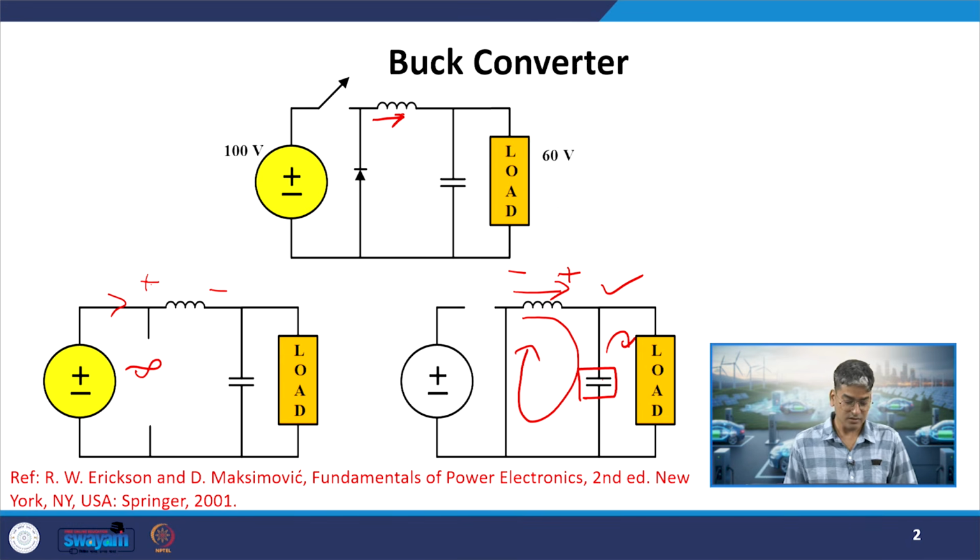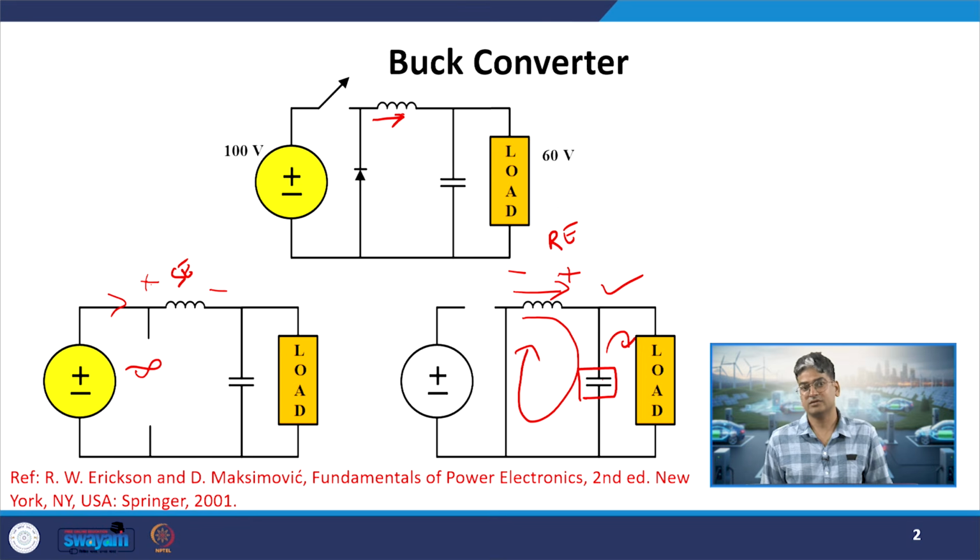Okay. So now coming back to the point which we mentioned while discussing our inductor, that it will be used as an energy storing component. If you see here, the role of the inductor in this circuit, during this stage it is storing energy, during this stage it is releasing energy. So here my inductor is behaving as a buffer energy storage element. It stores the energy when my switch is closed, and when the switch is open it is releasing the energy. So it is acting as a temporary storage of energy.